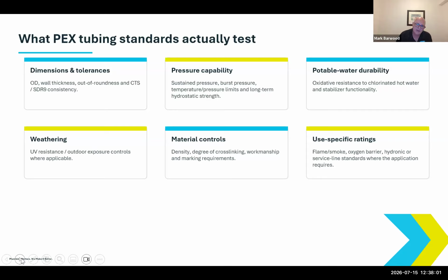Before you dig, you have to get the locator guy out, and if there's no metal on that pipe, you'd never be able to pick it up with this equipment. So just know there are some different pipes for water service lines, and we're starting to see a lot more PEX there now as copper gets too expensive.